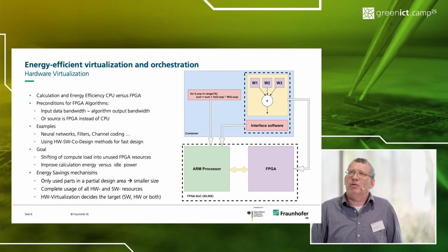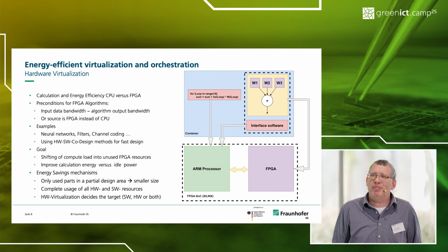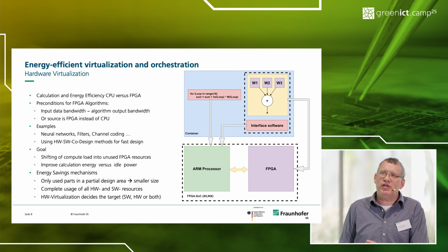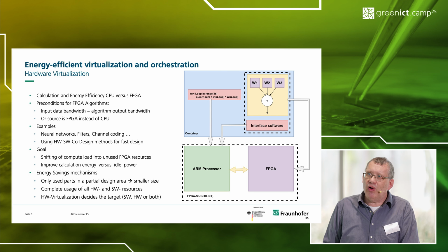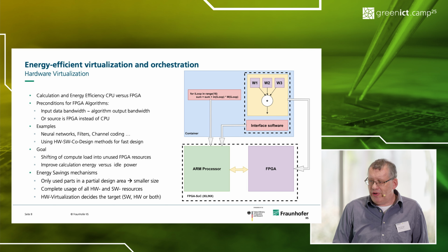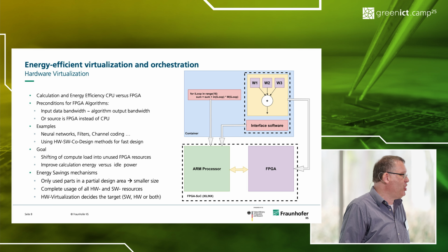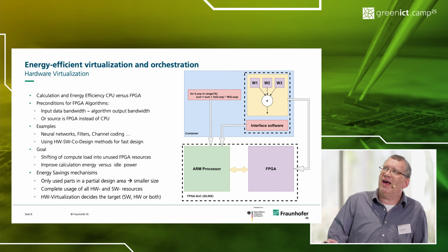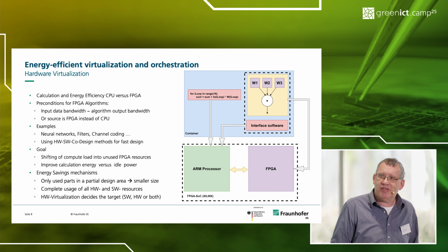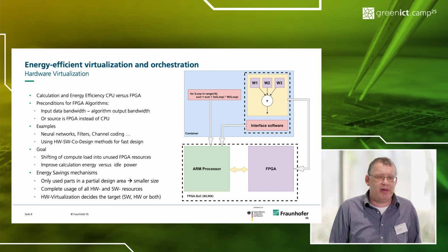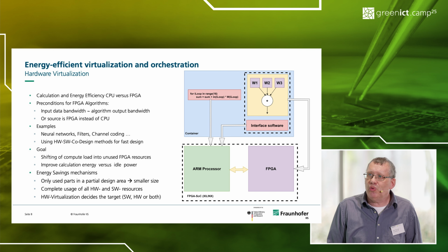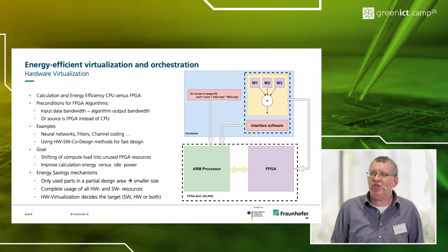And the functionality of hardware virtualization means that if you have everything in a container and you move the container, for example, to one worker node, then our framework analyzes whether there are free resources in the FPGA, and if this is the case, then the hardware part will be loaded into the FPGA, because the Xilinx FPGAs are partly reconfigurable, so at every time you can load a new hardware functionality inside this FPGA.